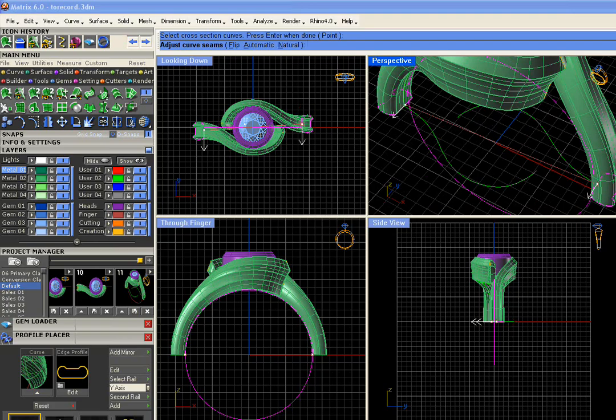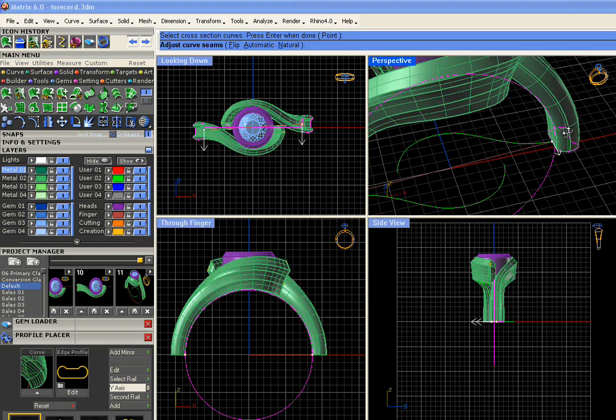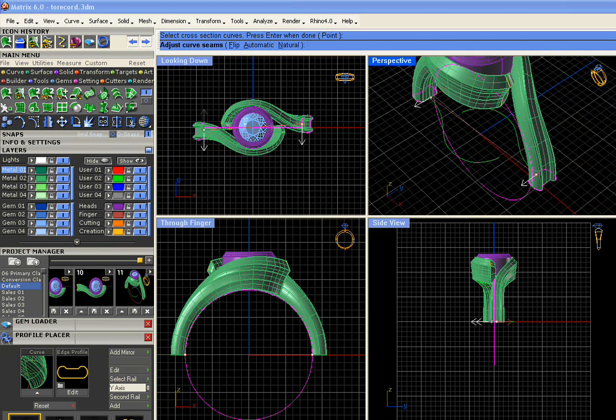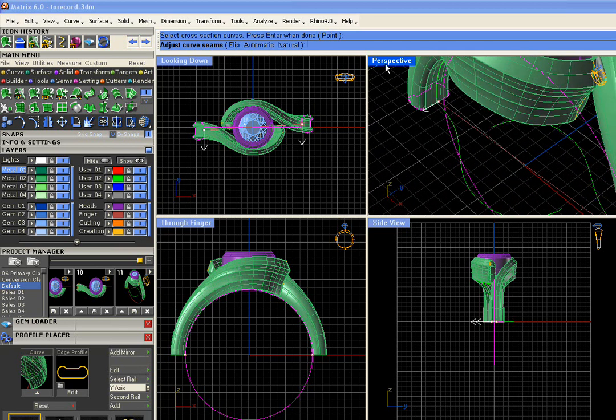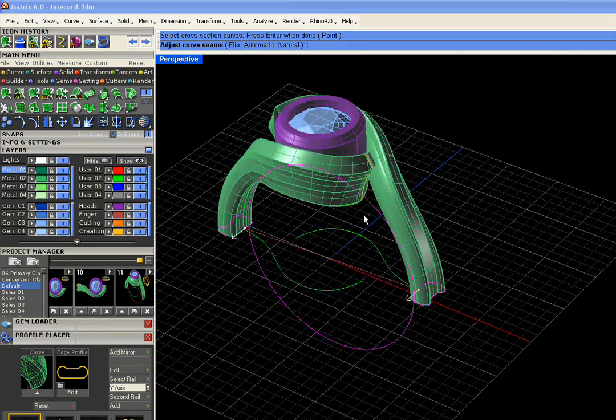Rhino sweep is really smart. It grabs a hold of these arrows and puts them pointing in the same direction. It also has to put them at the same location on the profile, so they're at the middle, pointing both to the same side. Now, in case you needed to move these on your own, we're going to show you how, because they don't always come out correctly.